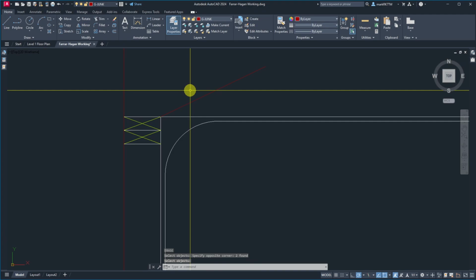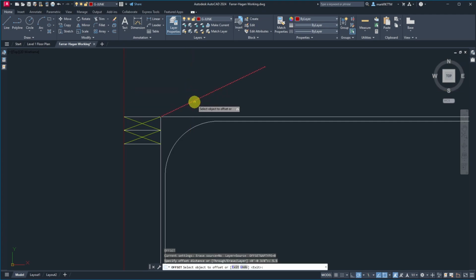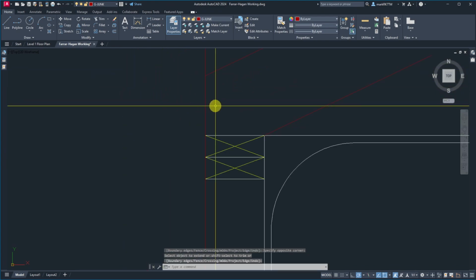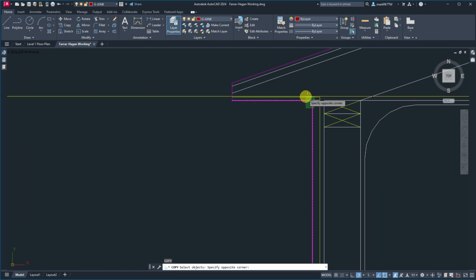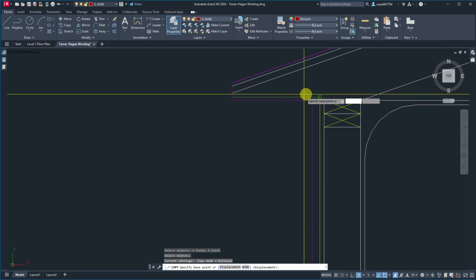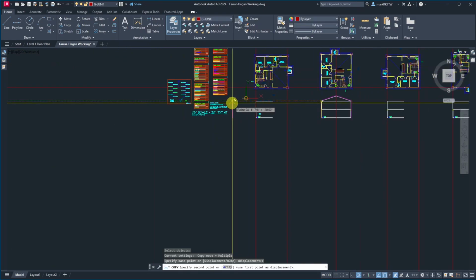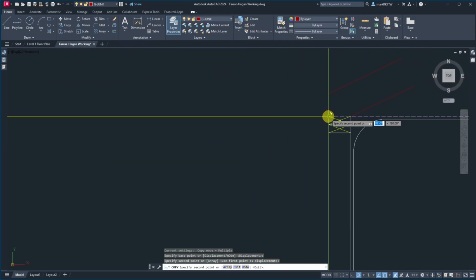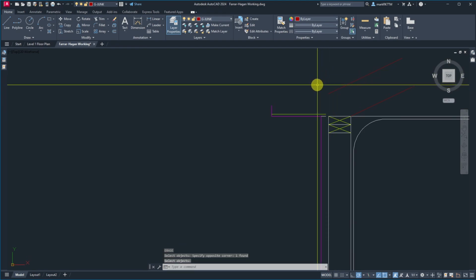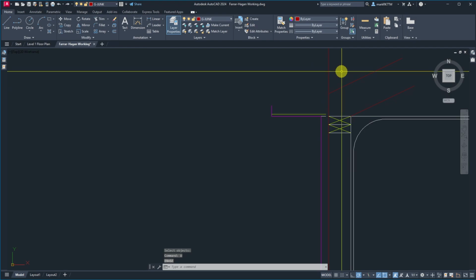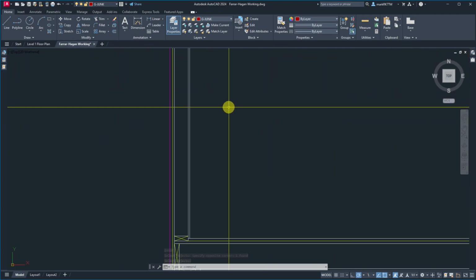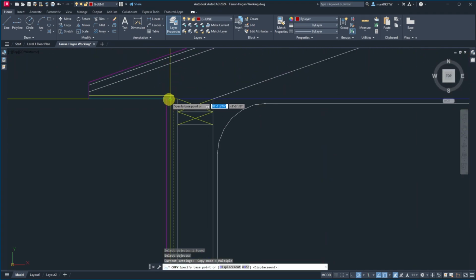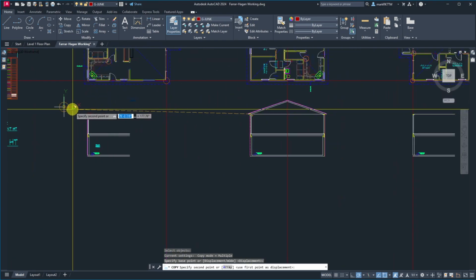I'm going to take that. I'm going to again offset 5.5. Get my joist. Extend out to here for the fun of it. Now, it's the same distances out. So I'm going to copy that and that from there to there. Now I can get rid of this line. Oh, undo. No, that's fine. So that one's gone, and I'm missing a line for my sheathing. So we'll just bring that out and put it on here.